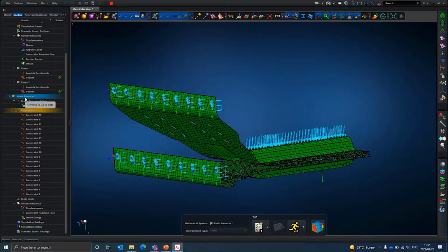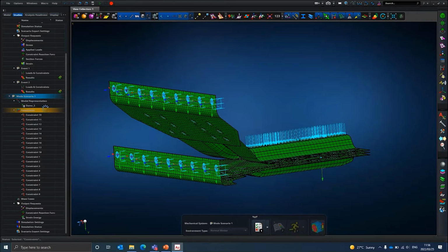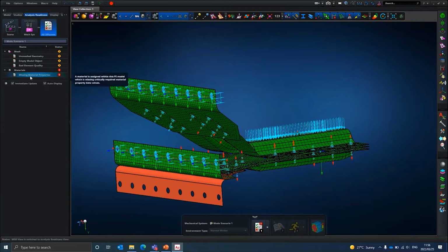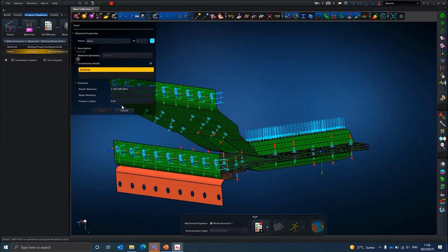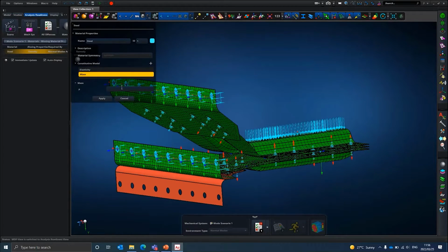And we, again, can just place it into the analysis scene. Now I expect one issue because I know I did not give a density to my material. So I can quickly add my density, and I just need to add the mass property. Here I just need to correct that because I want it in SI units. And okay.